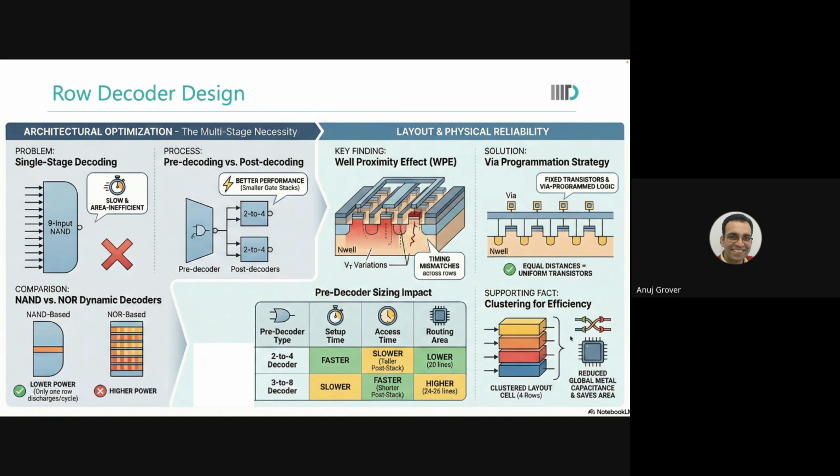So you remember this lecture on automation that we had with Ashu Talwar in the last semester? In that lecture, he told that in scripting or whatever layer you have in your layout, you can always identify through the layer map table which layer you are interested in. And you can put labels in a particular layer that you can define in your layout. You may call it a programmation layer.